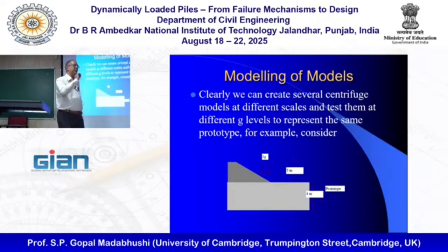But luckily, centrifuge testing allows you a way of verifying the scaling laws itself. And that is called modeling of models. To demonstrate this, what I've chosen here is an embankment 5 meters high, sitting on soft clay 4 meters thick, and bedrock below. That is the prototype problem we're looking at.